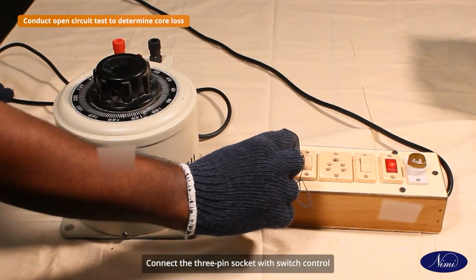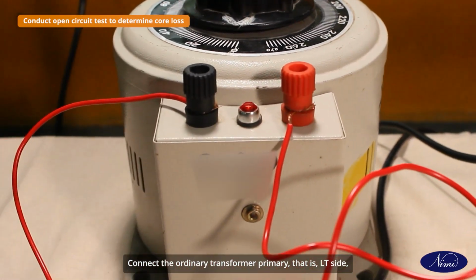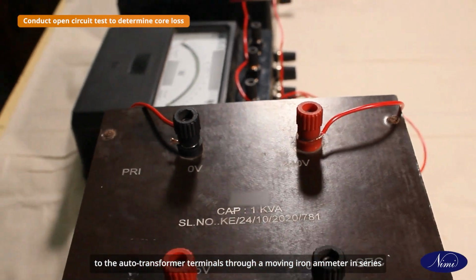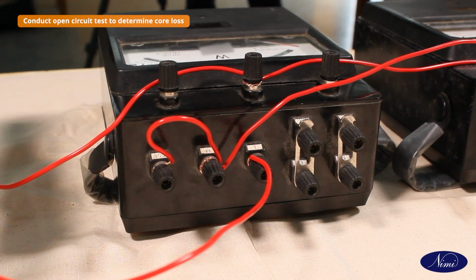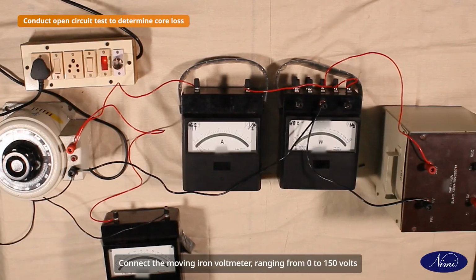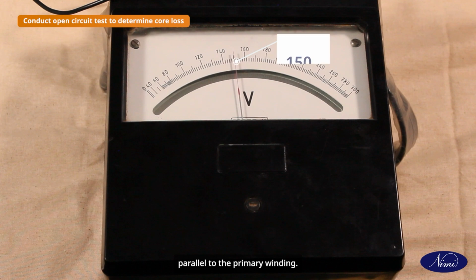Connect the 3-pin socket with switch control to the AC 240 volt 50 Hz main power supply and plug the auto transformer into the socket. Connect the ordinary transformer primary, that is LT side, to the auto transformer terminals through a moving iron ammeter in series and a wattmeter as shown in the circuit diagram. Ensure the current coil and pressure coil are connected in series and parallel as in the circuit. Connect the moving iron voltmeter ranging from 0 to 150 volts parallel to the primary winding.